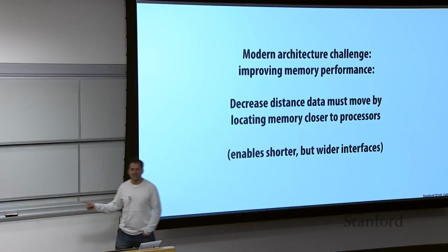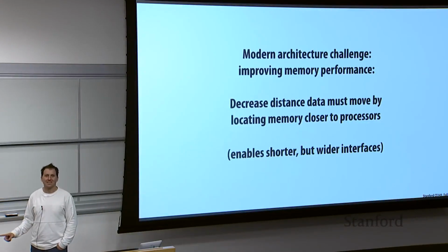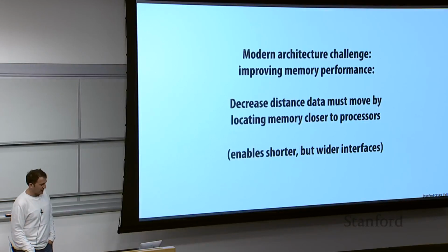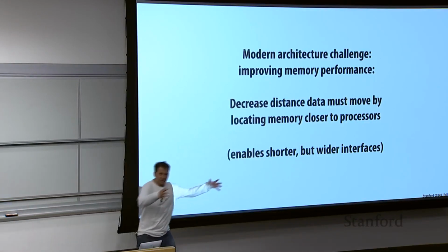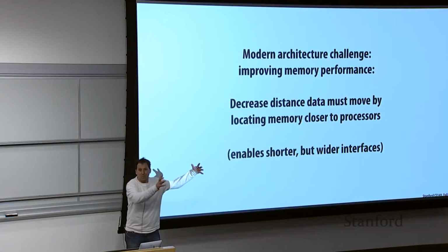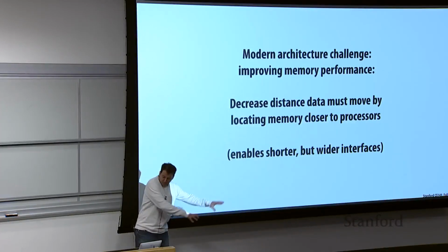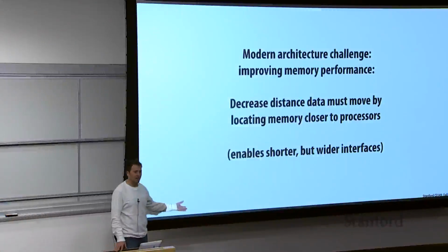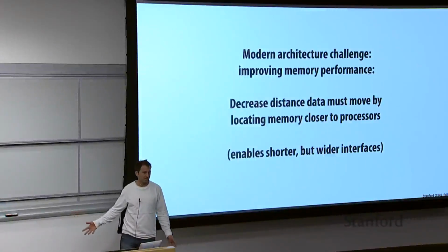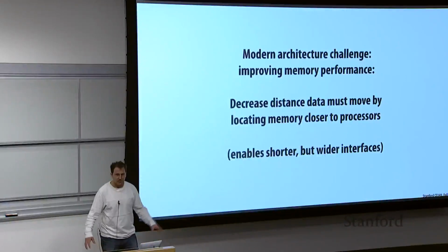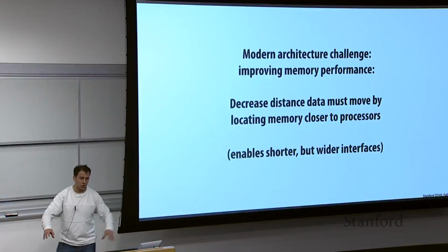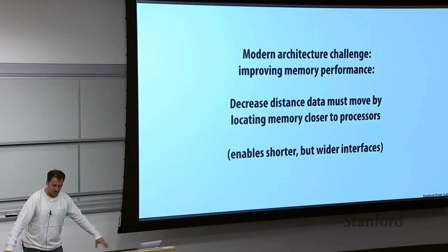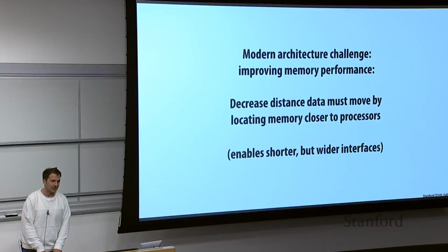All right, so now the problem, of course, is that we are bandwidth bound all the time. You can think about it as DRAM sits over here on the board, and then there are those pins, and those pins go over the entire board to the processor over here. Now, the problem is the only reason why we have 8 pins is that those are really expensive. To your question earlier, there's a lot of interest in bringing that processor a lot closer to the memory, so that the distance information travels is less, which makes it economical to build a lot more pins.